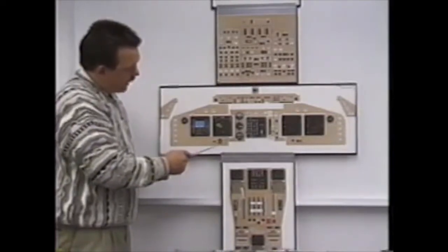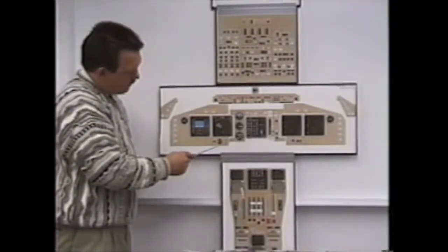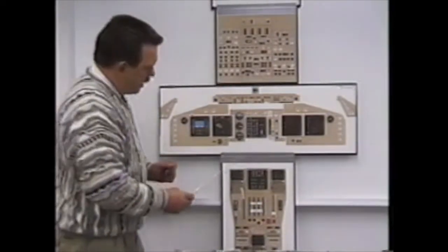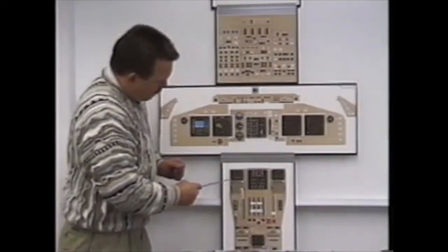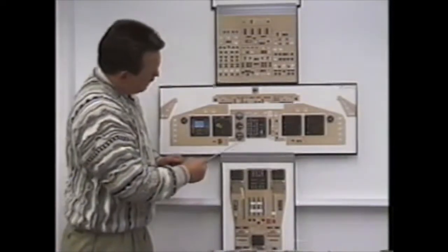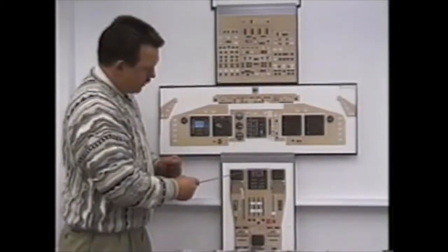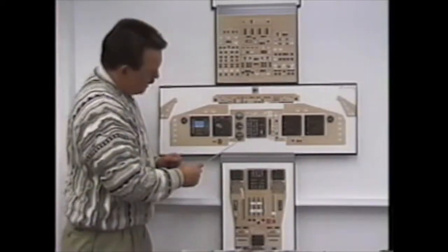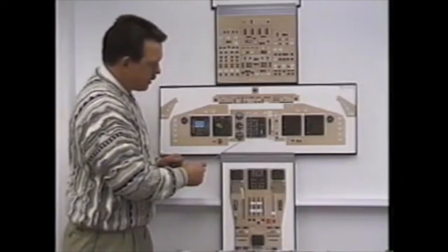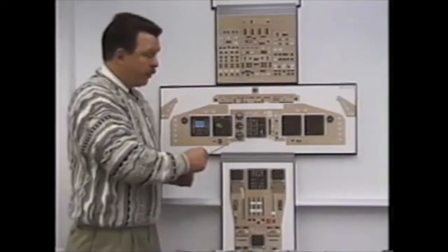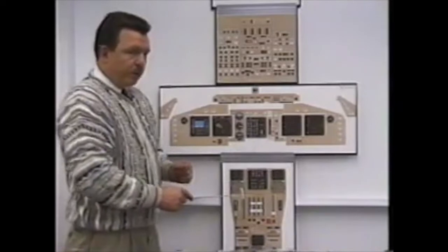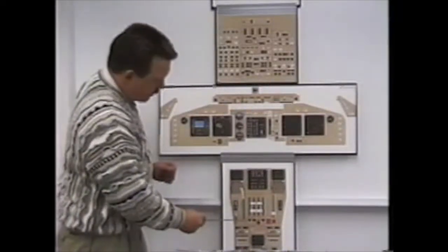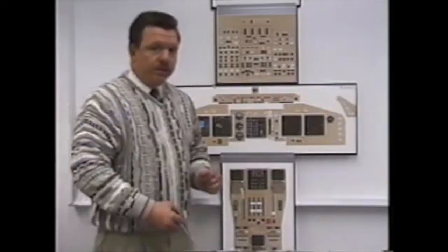Once the light off is indicated, we have to respect the 535 start EGT limit, which is indicated by the first red line. We must have an oil pressure indicated by 40% N2. We must have an N1 indicated by 40% N2. Once the first officer brings the fuel lever up to run, we have 2 minutes for the start EGT line to disappear, indicating that the engine is stable. If we encounter any one of those problems, electrical or pneumatic power interruption, immediate action for abnormal engine start is fuel lever to cut off and call for the QRC.